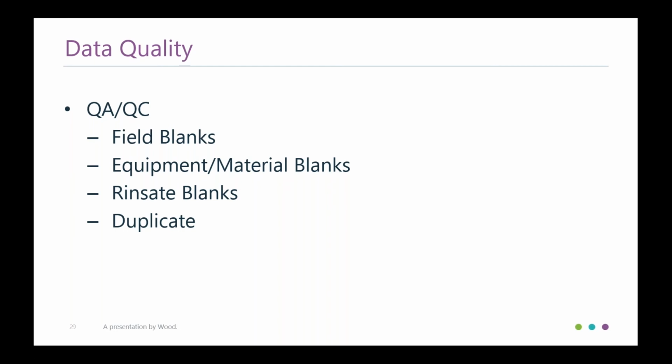And of course, this is going to have an effect on however many samples you collected with that equipment. Any results that you get from a rinse blank are going to apply to those. So if you collect 10 samples and then do your blank, those 10 samples have qualifiers with them based on the blank results. If you do it every time, you'll know it applies just to that one sample, but no one does that.